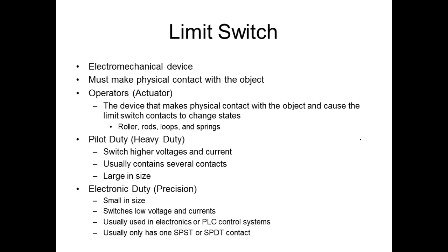We're going to have two types we'll talk about: pilot duty. These pilot duty switches are basically designed to run loads. Then we have electronic duty. These guys are basically used to input to programmable controllers. They're not designed to run loads. They just provide input. Are we okay? Yes, no?